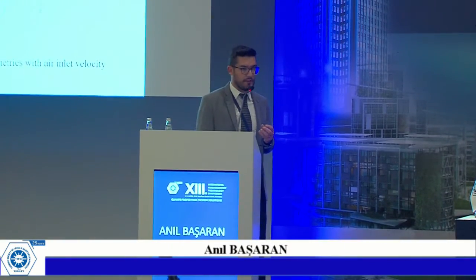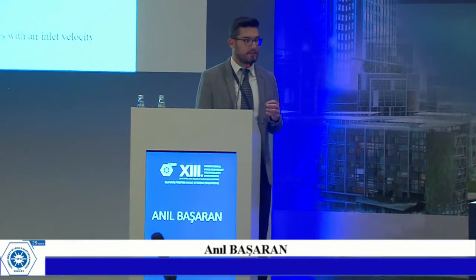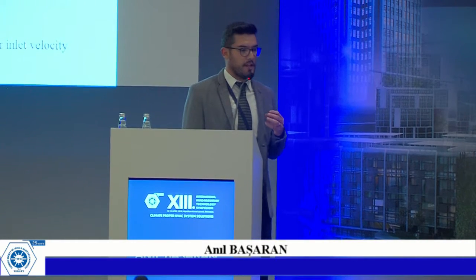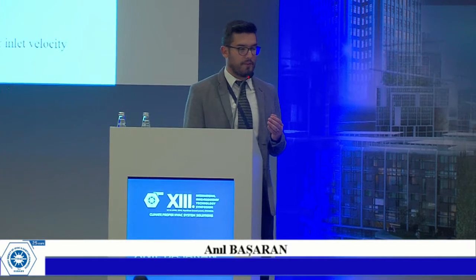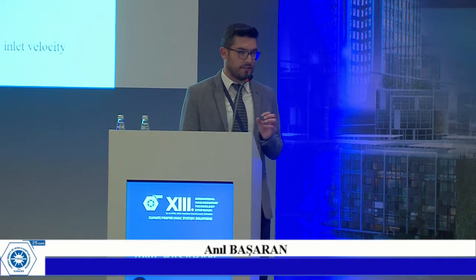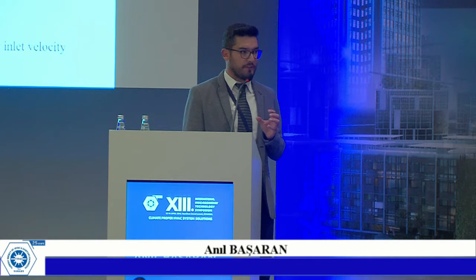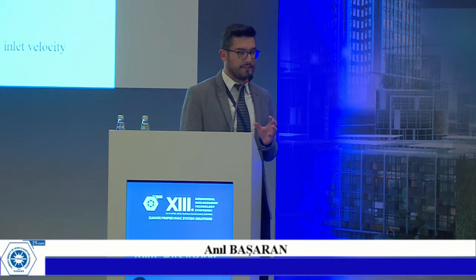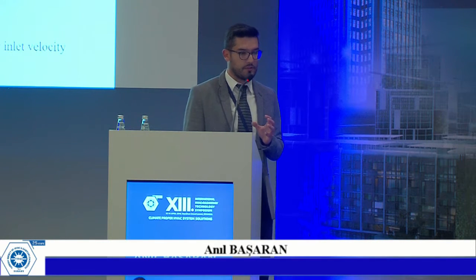Thank you for your question. Firstly, as I said earlier, we have only air velocity values for the existing refrigerator. So we calculated Reynolds numbers, and these Reynolds numbers, air properties and hydraulic diameter between the fins are in the range of laminar flow. So the flow is modeled as a laminar flow.